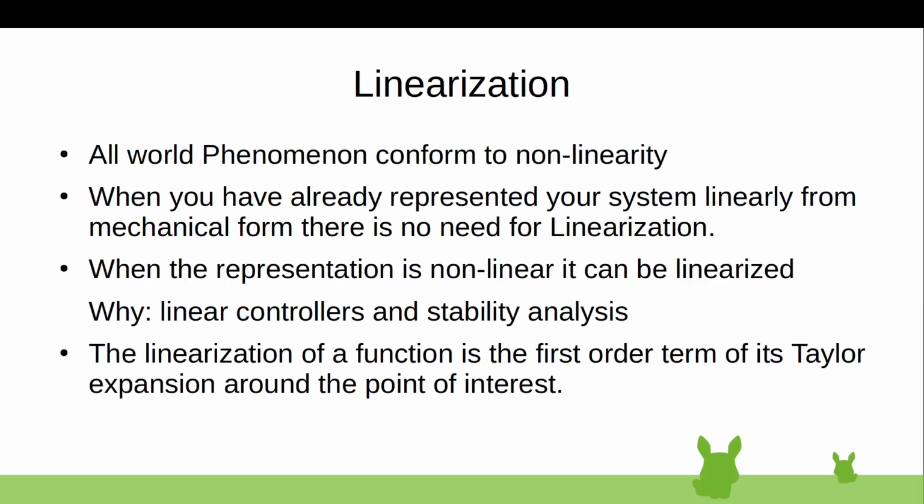So if you're okay with, for example, your nonlinear crane system operating at a 0 point, and you've linearized those equations, so you're using a linear controller for a nonlinear system, but you linearized your equations to be at that 0 point, then for the most part, you'll be okay. Although the further you get away from 0, the more likely it's not going to reflect how it is actually gonna act. So there will be a linearization error.